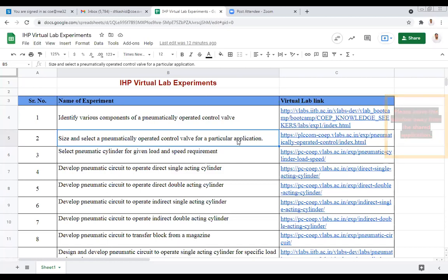We have seen the basic components of the hydraulic system and pneumatic system also. In the hydraulic system we need a pump. To store the excess fluid we need the accumulator, reservoir म्हणतो आपण त्याला. Then if we need to increase the pressure of the fluid, the intensifier or booster is one unit. Then to convert the fluid energy into mechanical energy, we need one important component, that is the actuator. That pressure energy you can call.